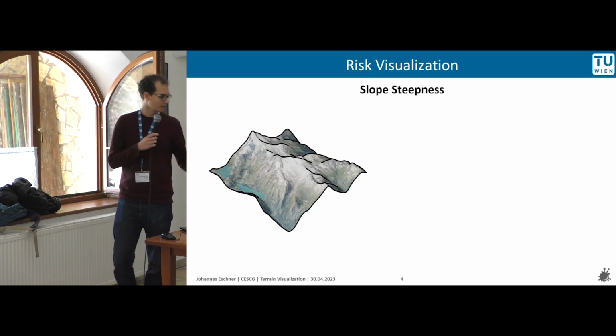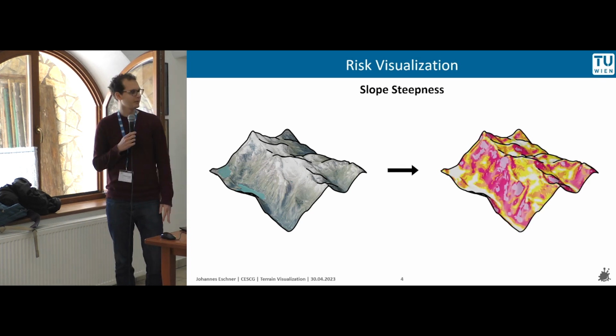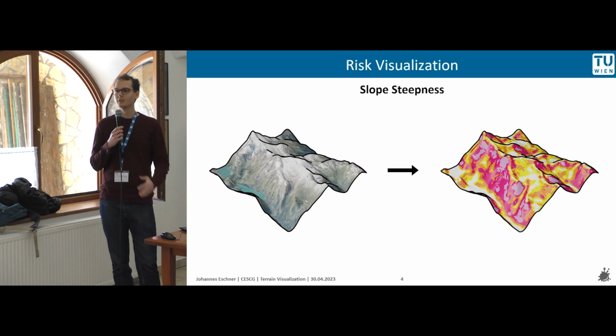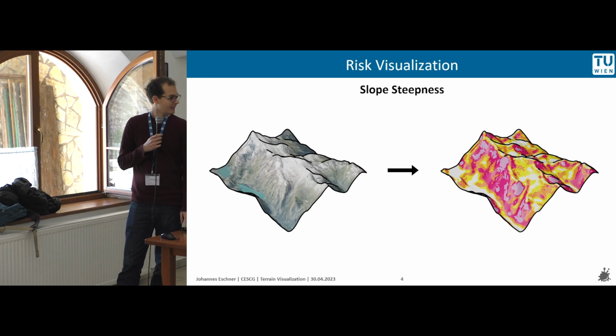So basically what I start out with is the terrain model. As Adam described, it works very similar to his renderer, where we just have a height map in this color encoding, and it displays as a grid mesh. And then I also put on an orthophoto so that I have a textured terrain mesh. And the first thing I derive from that is the slope map, where basically I just take the derivatives of this mesh, although I actually don't take the derivatives of the mesh. I'll go into that a bit later, because I don't actually need the mesh information.